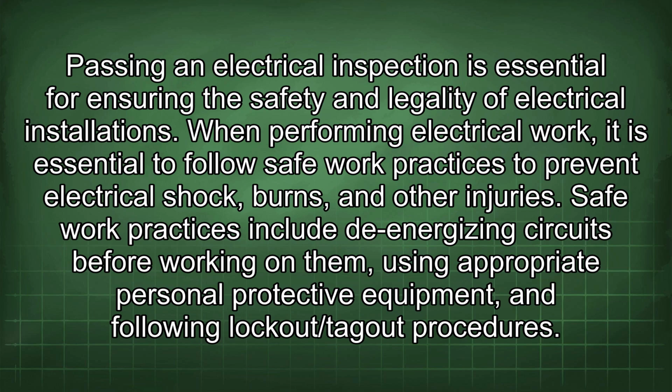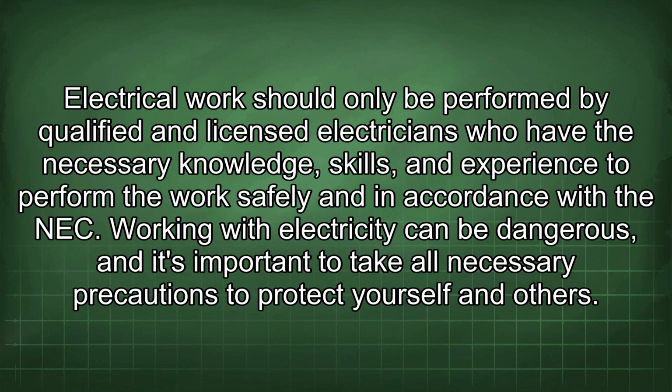When performing electrical work, it is essential to follow safe work practices to prevent electrical shock, burns, and other injuries. Safe work practices include de-energizing circuits before working on them, using appropriate personal protective equipment, and following lockout/tagout procedures. Electrical work should only be performed by qualified and licensed electricians who have the necessary knowledge, skills, and experience to perform the work safely and in accordance with the NEC. Working with electricity can be dangerous, and it's important to take all necessary precautions to protect yourself and others.